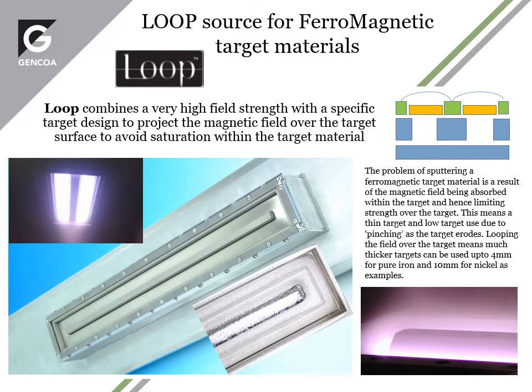Loop sources are a solution to the sputtering of ferromagnetic materials. We do sputter ferromagnetic targets with two poles, high strength versions, and that works, but the target use and the thickness of target is very limited.